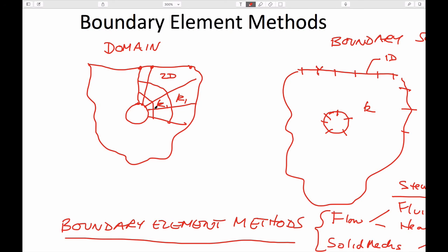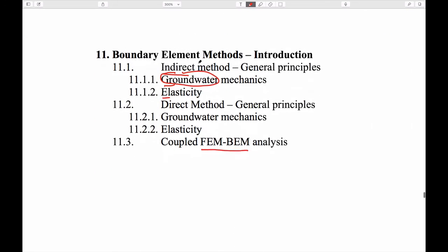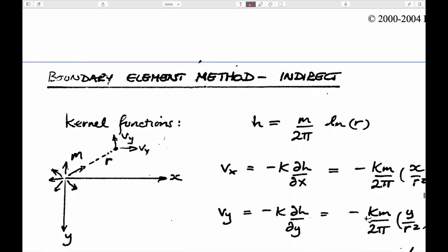Then presumably what we could do is use a domain that has finite elements on the inside and then grades on the outside to take it to infinity with boundary element methods on the outside. That way we'd get the benefits of this nonlinear response on the interior where it works at its best, but also be able to represent this medium that goes to infinity and beyond, outside that, by this somewhat more effective method where it's essentially linear outside. And so you could think about combining the two methods to be able to do that. So that's the deal.